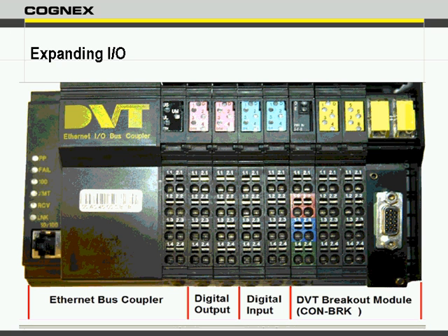One thing to note: all these things are outputted from the camera via a running mode or inspect mode. If this inspect mode is not active, we're not going to be able to communicate outside the camera. So realize I'm triggering right now. The scripts are working within the program, but they are not outputting from the camera. In order to have that, I must have this button Inspect on. Then when I trigger this, it goes through the whole result table and the script and outputs the results. As we can see, script 1 and script 2 are going high right there.